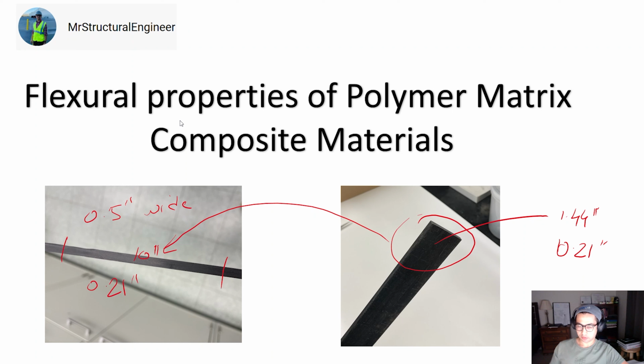The selection of length for the 3-point bending test depends on various factors, and for that you might have to look into ASTM D7264.